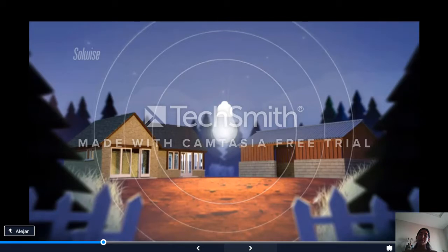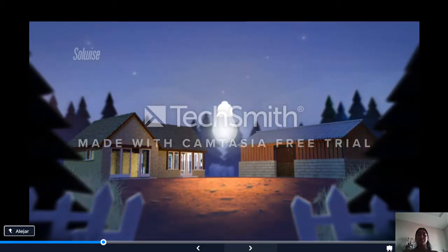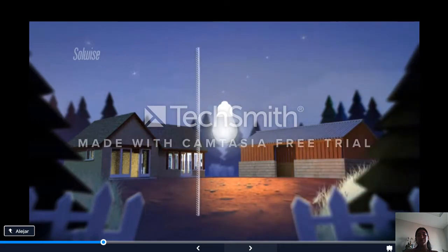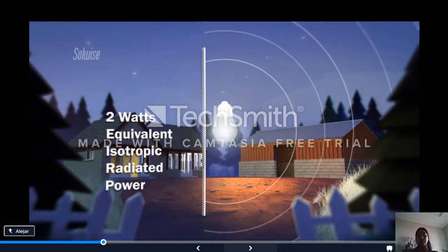Now imagine our light isn't bright enough for us to see. We can't turn the power up, but we do notice that a lot of the light from our bulb is going in directions that we don't need it to. We decide to bring a mirror up behind the bulb so that all the wasted light going in that direction is reflected forwards. We have effectively doubled the brightness in front of the bulb. It is now equivalent to a 2 watt bulb. We express this as 2 watts equivalent isotropic radiated power, or EIRP.